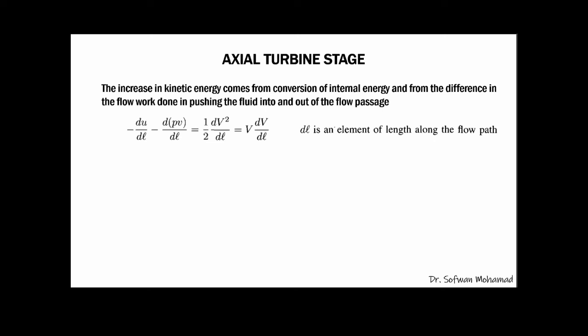This equation shows that a drop in the internal energy increases the kinetic energy of the flow, as does the net PV work term in this small section of the channel.